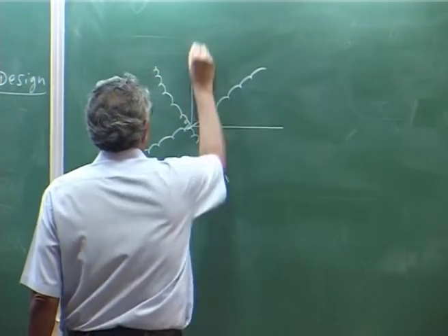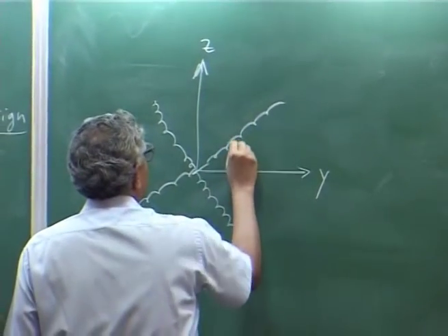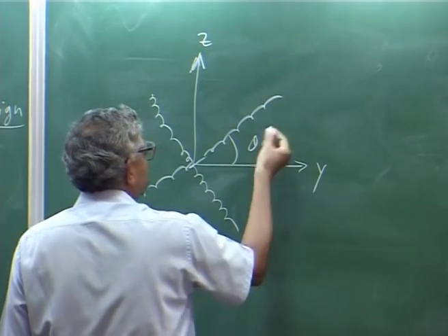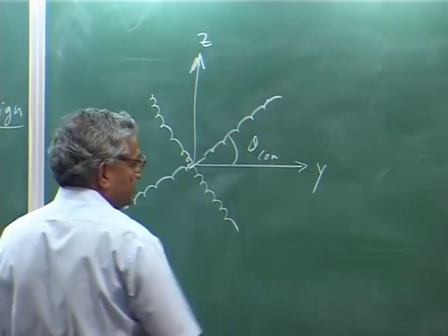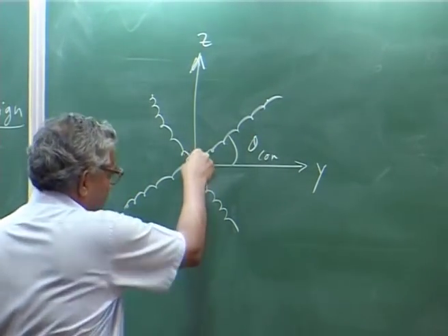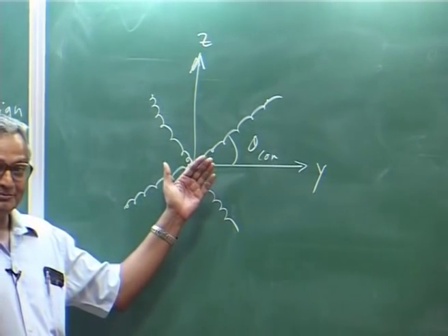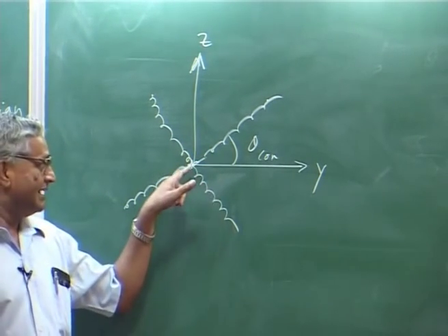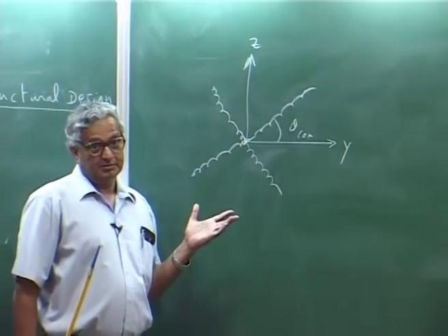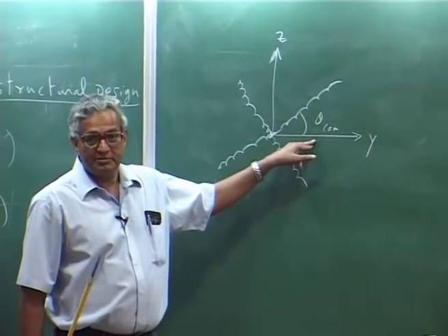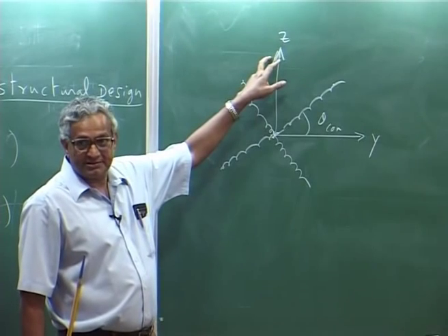And this is my hub, and this is my theta control or theta pitch angle, whatever it may be. Spring is changed and my blade may be coming out like this. That means I am having my pitch bearing inboard of this. So, what is flap? Flap is rotation about y axis, lead lag rotation about z axis.